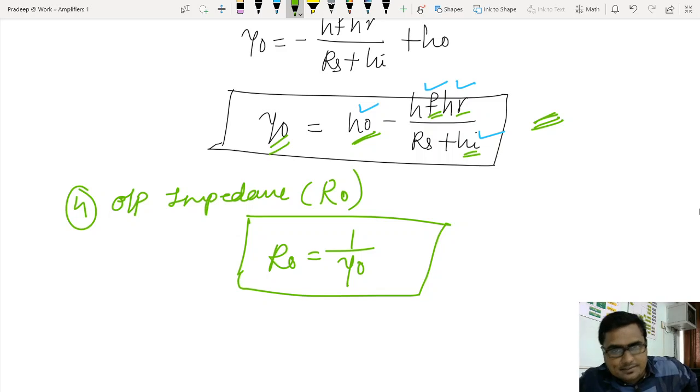Let me tell you an example. Think about HF. Think about that HFE parameter or beta. Generally, if I'm in AC analysis, I will write HFE. If I'm analyzing the common emitter configuration in a DC scenario, then I am supposed to use beta.